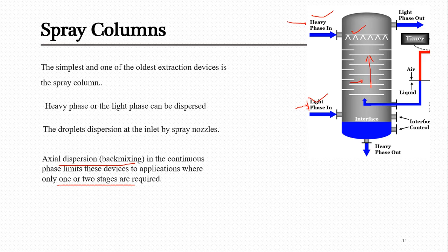For example, this is some organic liquid and it attracts benzene. When it starts moving towards the top, this benzene which it has attracted from the feed can be released again towards the feed. That is called back mixing. It is back mixed with the original stream from where it was coming. At this point it was transferred to this solvent, but after some time, when it moves towards the top, it gets attracted again towards some component of the feed and goes back there.